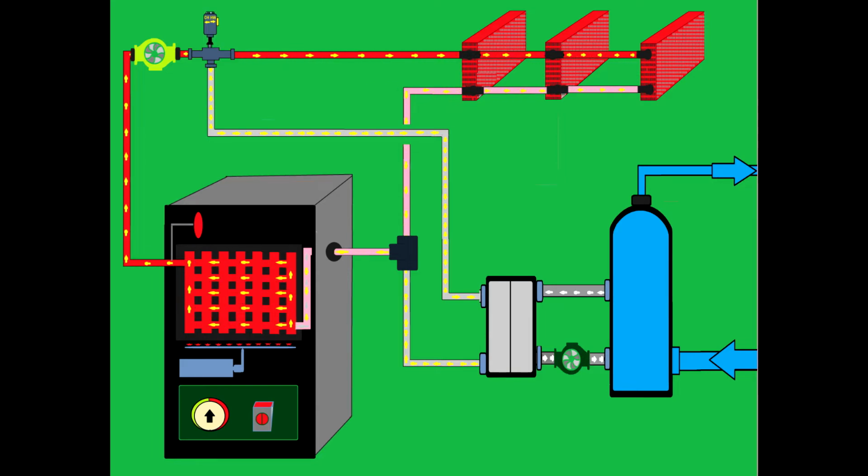The boilers have a thermostat which controls the heating agent temperature, but the room also has a thermostat which controls the air temperature. So as long as the room thermostat is on demand, the boiler will run to keep the agent heated at a specific temperature. The boiler thermostat does not care about the rooms. It only takes care of the heating agent temperature. Remember this.